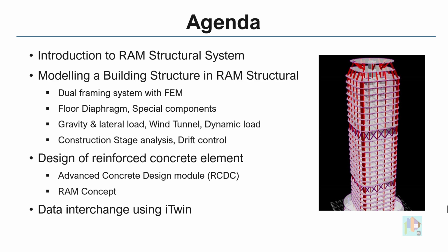I'll start with a basic introduction and some useful features of this product required for any building structure, like consideration of dual framing system with floor diaphragm, inclusion of wind tunnel data, construction stage and drift analysis. For concrete element design, we'll use multiple interconnected modules including RCDC and RAM Concept. How we can transfer the model and analysis result to these modules and perform concrete design will be covered,